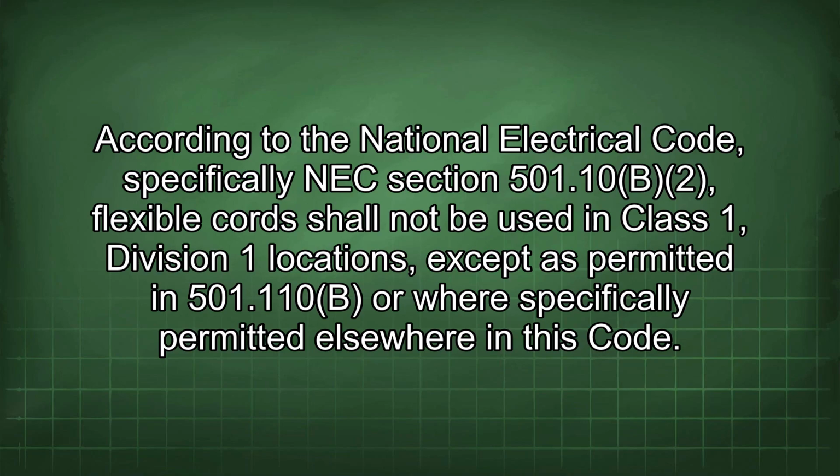According to the National Electrical Code, specifically NEC Section 501.10(B)(2), flexible cords shall not be used in Class 1, Division 1 locations, except as permitted in 501.10(B) or where specifically permitted elsewhere in this code. Exception.